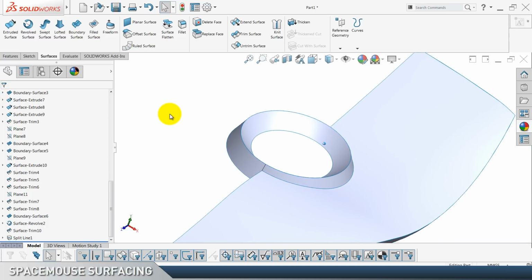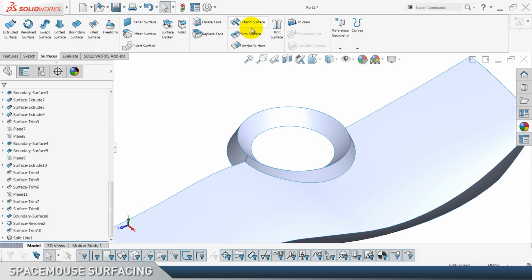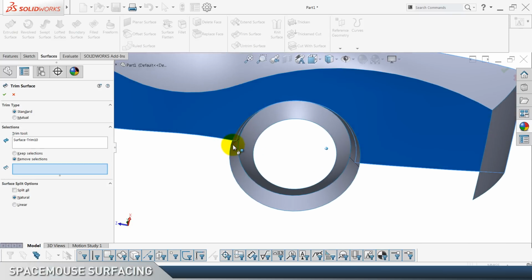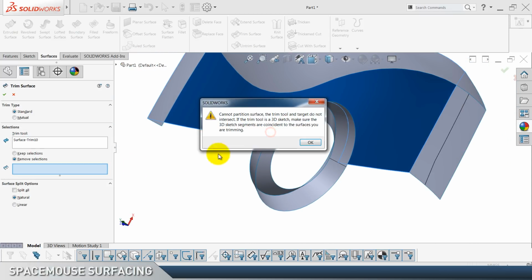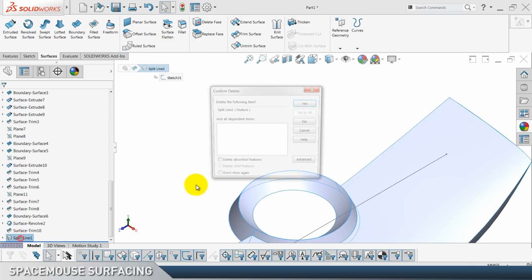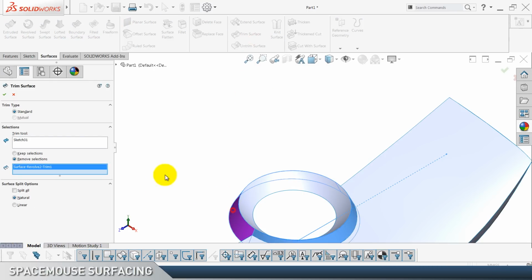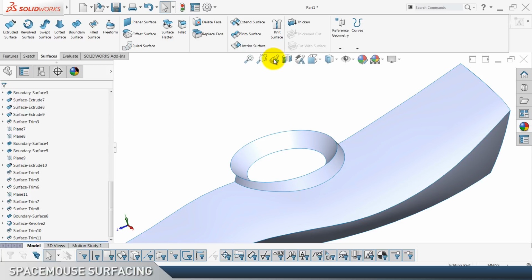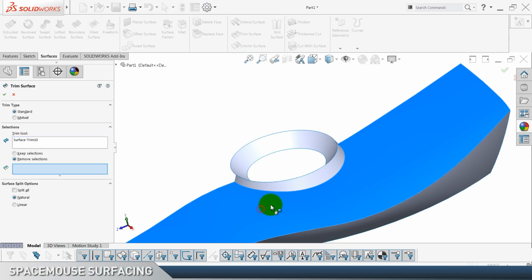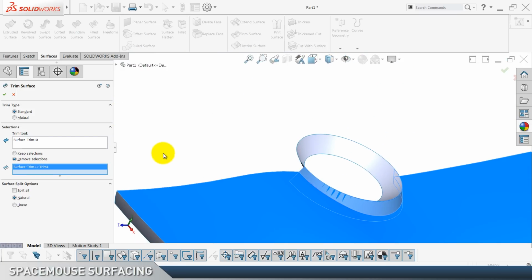Okay, now let's actually try trimming. Trim tool is this one, and remove this bottom piece. No, it's not gonna work again. So let's actually delete this split line and use this sketch as a trimming tool for this one. Now we are gonna definitely be able to trim out this piece. Okay,